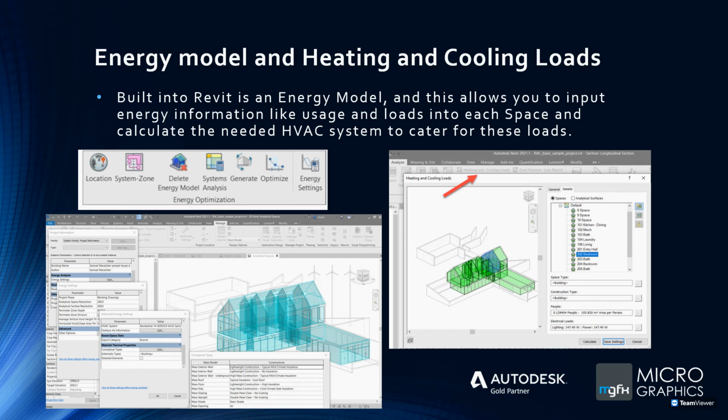Your building has a certain orientation. It has a number of people and the usage or occupancy of that particular space. It's got some electrical load, so if there's machinery or computers or whatever in that particular space, all of these factors contribute to the heating and cooling load of that particular space.